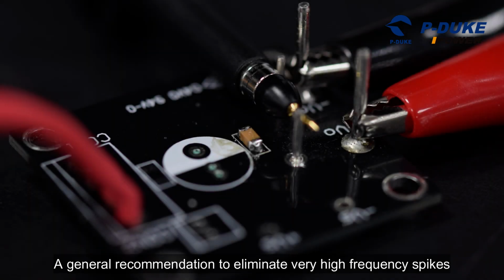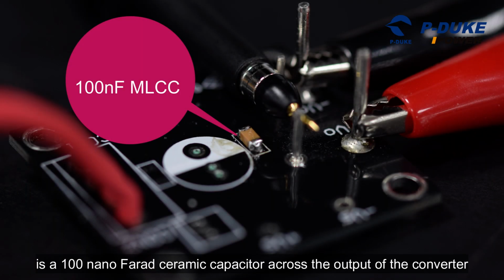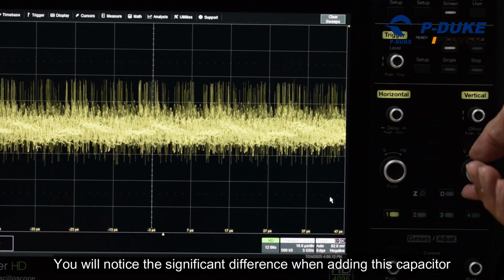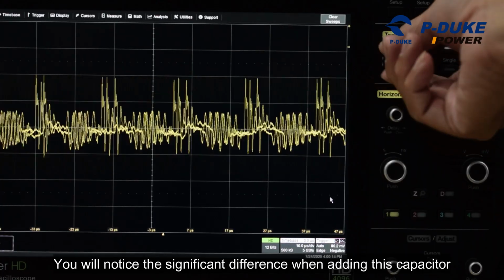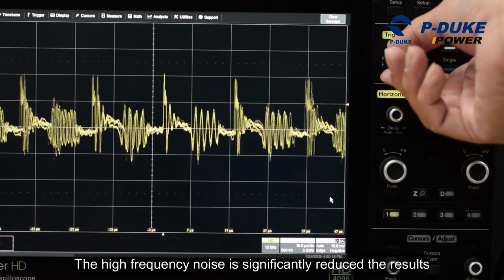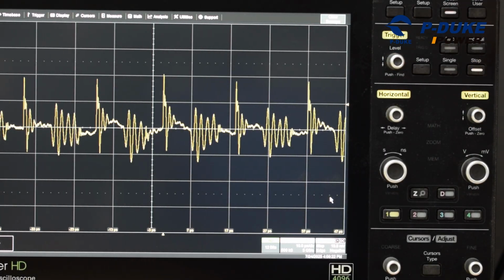A general recommendation to eliminate very high frequency spikes is a 100 nanofarad ceramic capacitor across the output of the converter. You will notice the significant difference when adding this capacitor to the measurement setup. The high frequency noise is significantly reduced. The results correspond more closely to the real values.